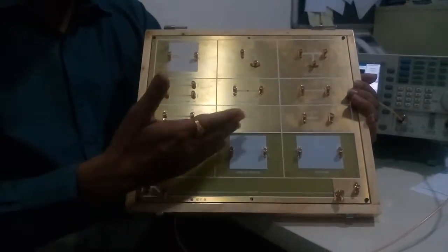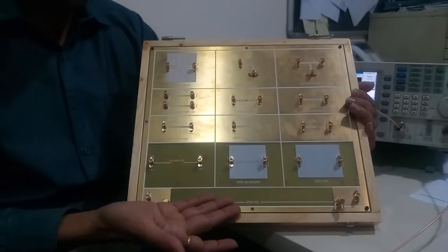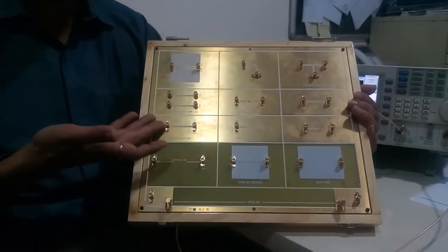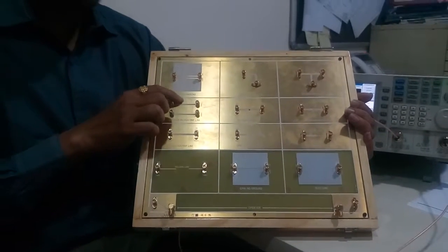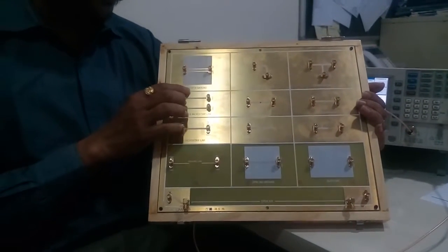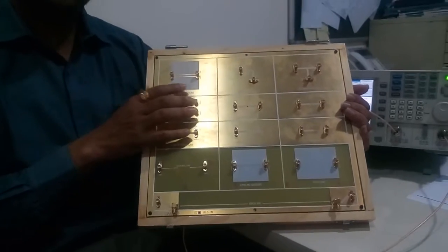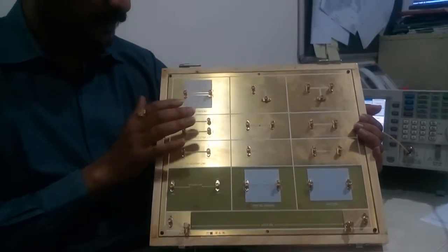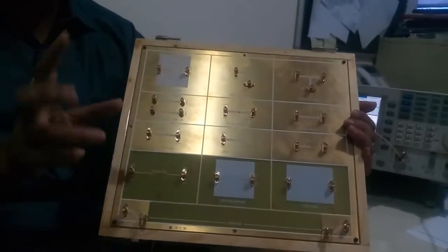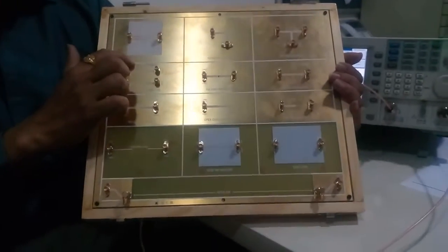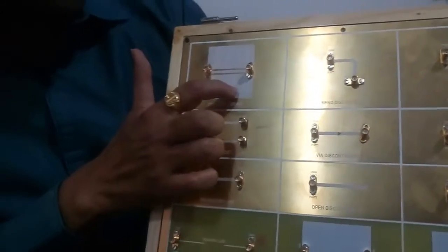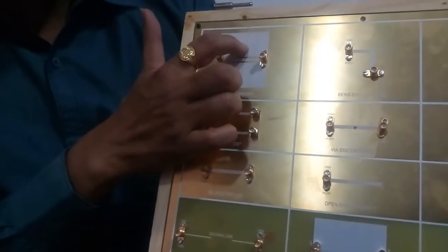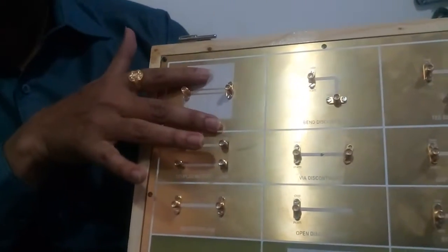In our earlier video we covered the open air transmission channel, coaxial transmission and microstrip. Now we are going to demonstrate the CPW, coplanar waveguide. Coplanar waveguide is a transmission channel which looks close to the microstrip, but there is one difference: here you can see the CPW with ground. With ground means this is the microstrip line, but the ground is placed at this side and this side. So on both sides the ground is very near.